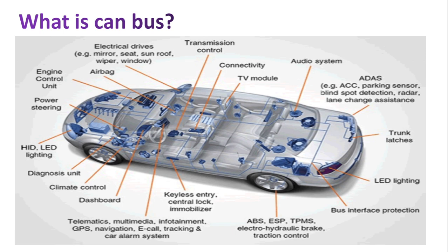Okay, so the first problem that will occur is magnetic interference, the second will be short circuit, because a large number of wires are there, so a large short circuit risk will be there. And identification of the wires becomes troublesome, right? And the cost of the wire is also a main factor, because the more wire you use, the higher the cost will be, right?